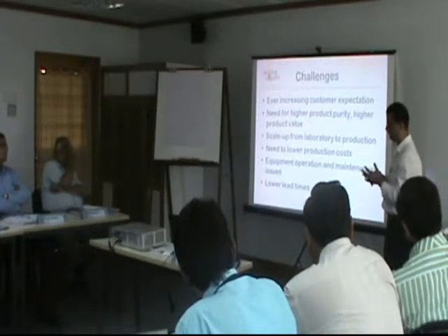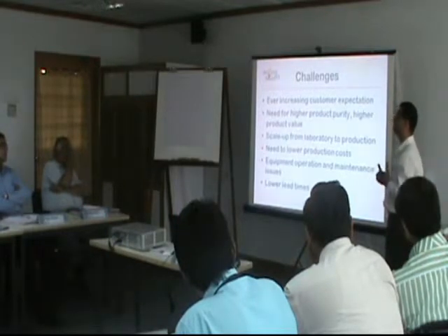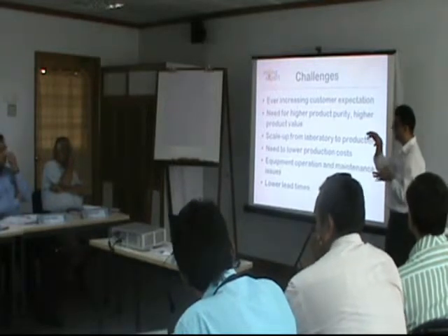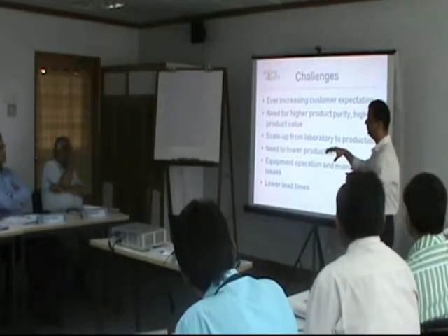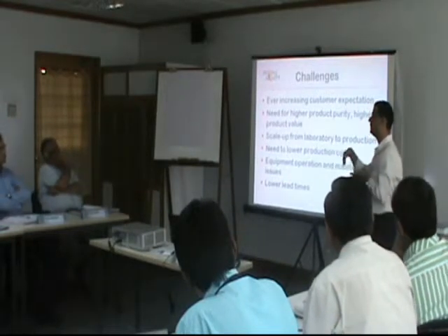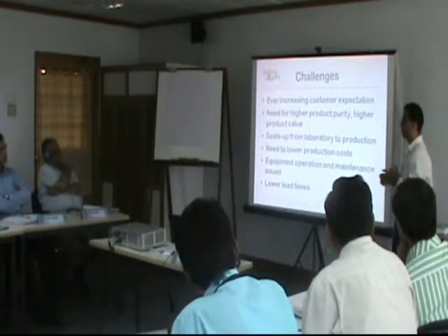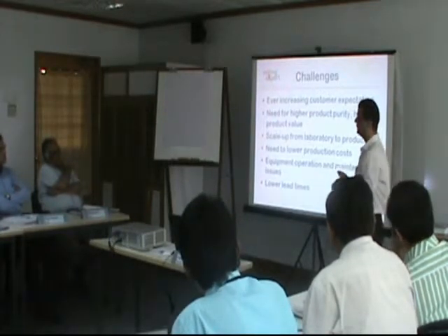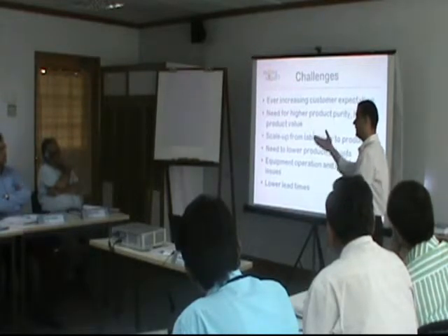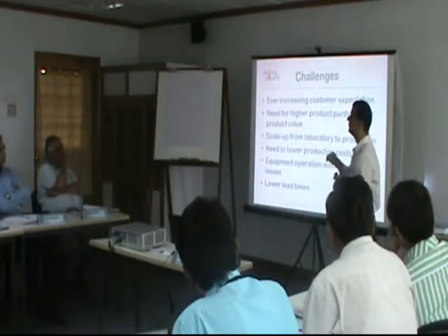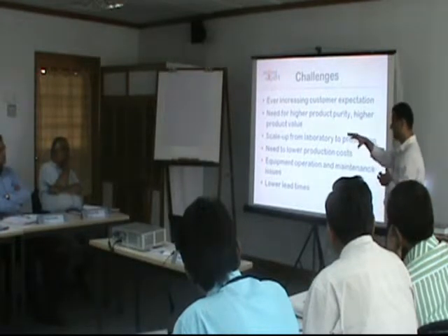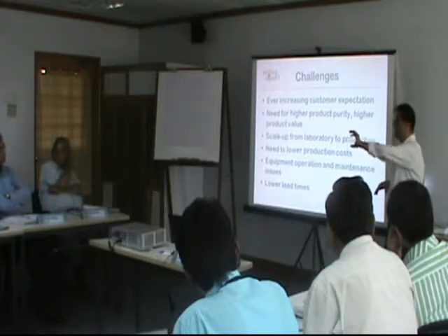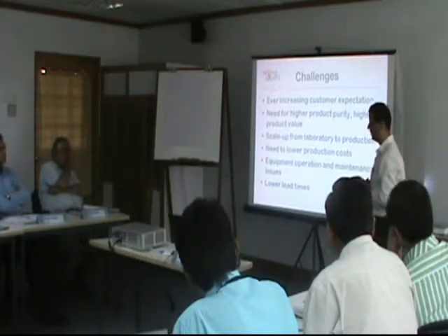When you have materials of different bulk density, there are different mechanisms of mixing, as we will see moving forward. There is diffusion mixing, there is convective mixing, there is shear mixing. Depending on the material characteristics, the applicable principle of mixing differs. Diffusion mixing is basically tumbling, like the V blenders. There the prime force acting is gravity, and with gravity there is a very good chance of separation. That is the reason that for materials with varying bulk densities, convective mixing is used, and shear mixing is used where the materials are very cohesive.